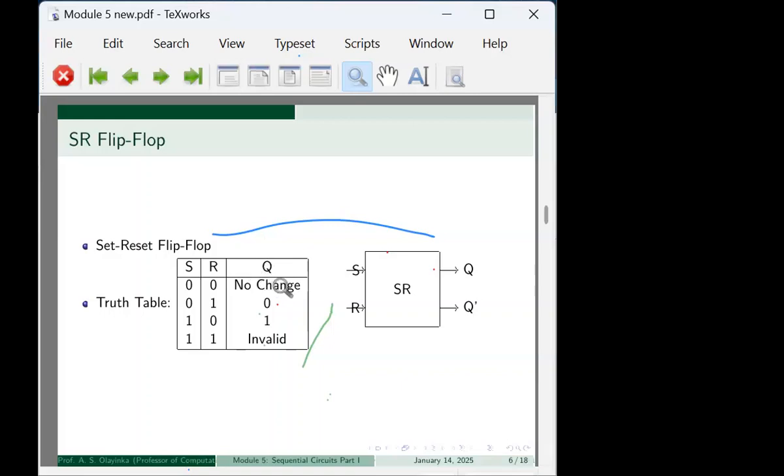And the next state here, instead of having any signal, will just give me whatever the previous state is. No change. It will just give me the old state, meaning my Q of T will be equal to my Q of T plus 1. This one gives me the old state as it is, and this one is an invalid state. When you come to this Q prime, you will also have similar results, whereby this one will become an invalid state, and this one will become a no change, which will give you Q of T.